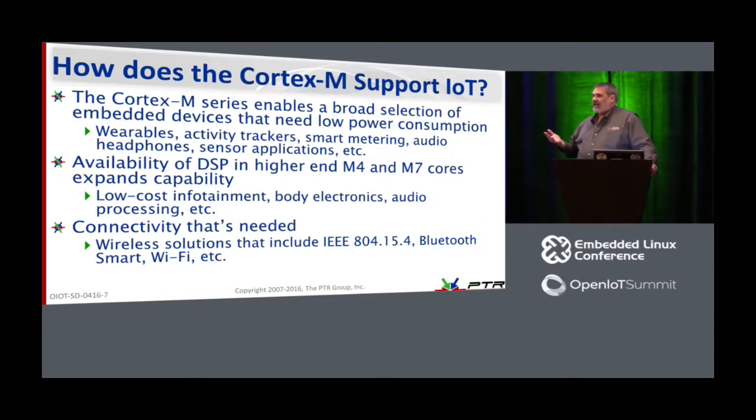So we're finding in many cases that there are a lot of these edge sensors that we don't need an operating system on. Operating systems add complexity. And if you're thinking in terms of security, the more complexity you have, the more likely you are to have screwed up somewhere along the line in the security piece. They present a larger attack surface. The larger the attack surface, the more likely you are to be hacked. So in the case of the edge devices, the smaller we can make them, the dumber we can make them, the smarter they are, right? So we're trying to make a dumb device smart.